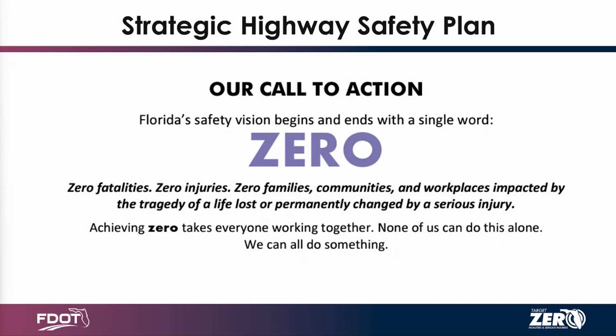So, personal experience. Last fall, we had some family friends that lost both of their children. They hydroplaned and ran into a concrete pole, and both children died. When I look at it as an engineer, and I'm not going to put this in writing, but I'll say this here, the pole was inside the clear zone and it was unprotected. It was raining at the time, and when I drove out there, the shoulders were built up. While there is a good cross slope, the water can't get off the road.